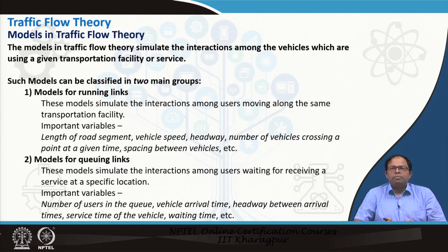That basically points towards what is flow in a particular corridor, what is the concentration in a particular corridor, and what is the speed or travel time in that particular corridor. And speed or travel time is basically the impedance that we are talking about. So based on different loading patterns in a corridor, this impedance will also change, and this actually plays a role in traffic assignment.